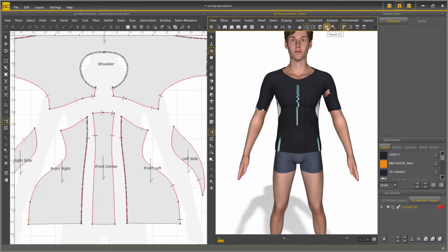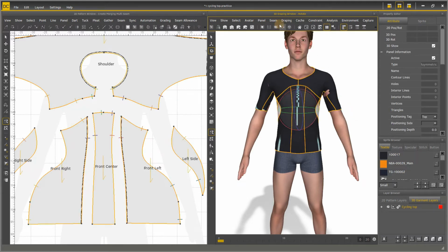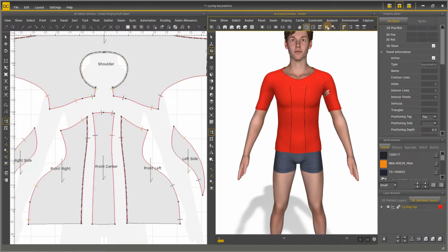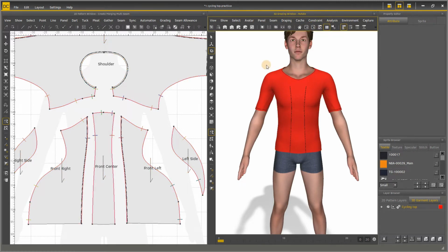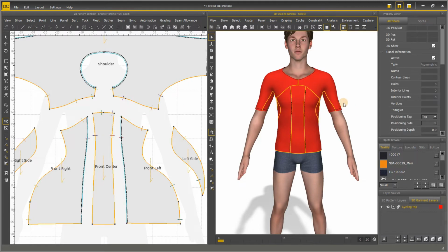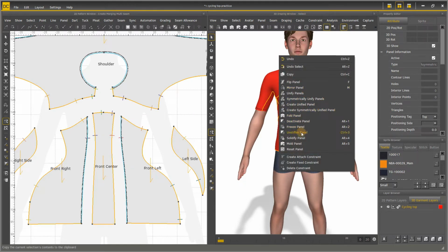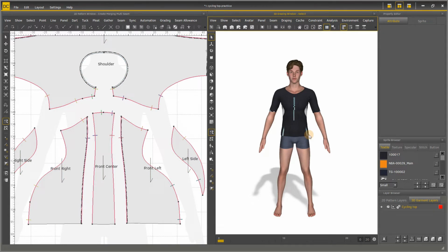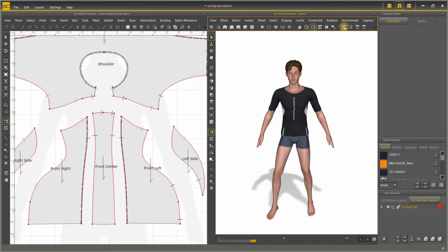If the garment is not dressed well, we can use the Stiffen Panel function again to stretch the tangled part of the garment. And unstiffen the panel to simulate again. The garment will fit better after doing this. Then click Dynamic Play and enable Catch to play the animation.